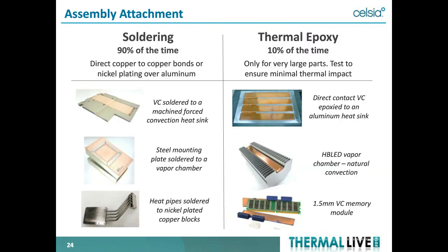Assembly attachments, I think it's safe to say that over 90% of the applications use solder. It does a couple things. One, it gives you a good mechanical joint as well as a good thermal joint. And the key there is the thermal joint. The aluminum parts are nickel plated so that they're directly soldered between the copper and the aluminum parts using the nickel.